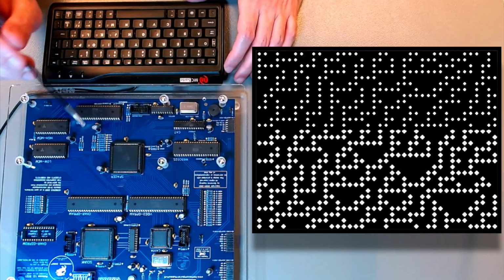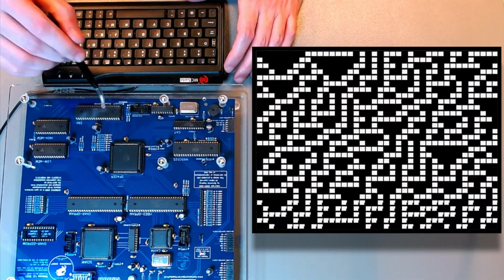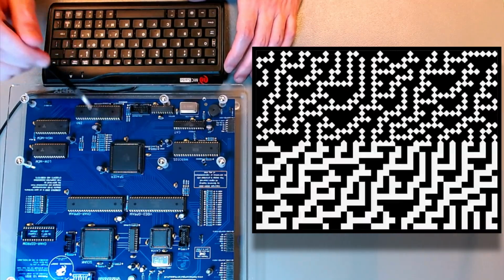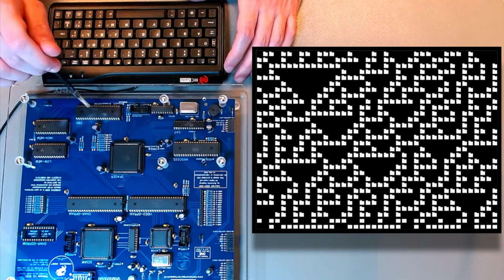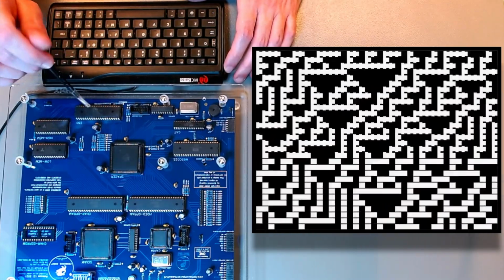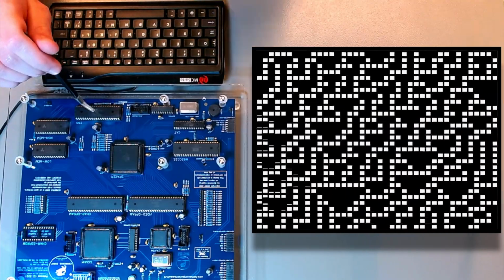So it goes a lot faster, not to mention the fact that the Z80 has hardware optimized memory transfer instructions. It can move entire blocks of memory from one position to the other very quickly because of these hardware optimized instructions like LDIR.